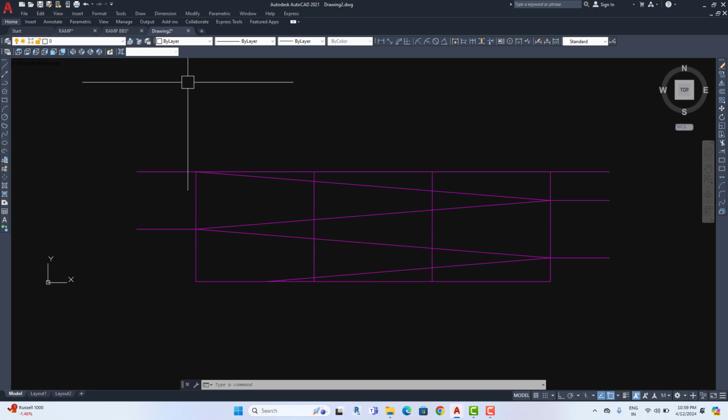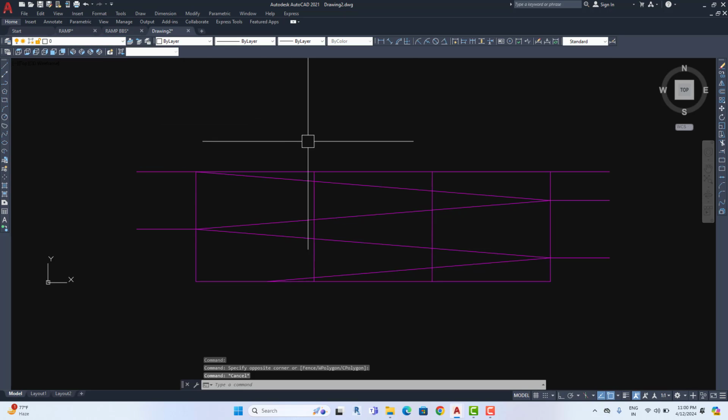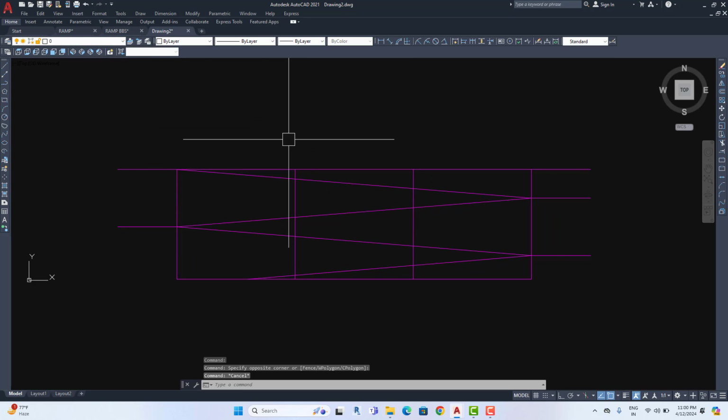Sometimes if I'm transferring only center line, but in the layer page, the rest of the layer content also gets copied here. But unfortunately, for the good thing, the unnecessary parts are not coming here. But I'm going to tell you, if after this center line, unnecessary content comes to the original file, then what you will do? The purge is a must. And how to do the purge, I'm going to tell you.